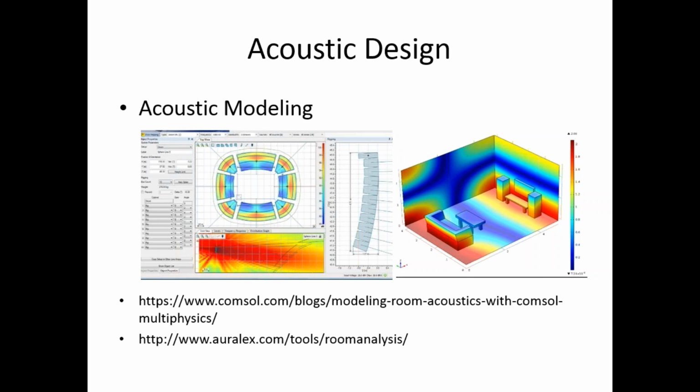So what I would do is I would work with a cabinetry maker, and then I would end up picking some type of, and we'll come to this, acoustical fabric, if it was a speaker system, that would be reflective that I would apply to the front. I would try to figure out the venting, knowing that heat rises and cutting slits in the back in the upper portion, but my AV person informed me that you don't just need to vent at the top of something, you need to vent at the bottom so that you get cross circulation when you're dealing with heat venting out the back.